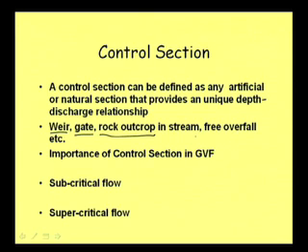Then on the hilltop I did not have any other devices, but I could find a rock outcrop, and by measuring the depth of flow at that point, I could calculate approximately how much the discharge can be. Well, so those sorts of situations are there. Then sometimes there can be a free overfall, and all those points we sometimes use as a control section.